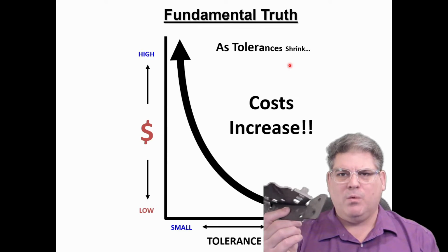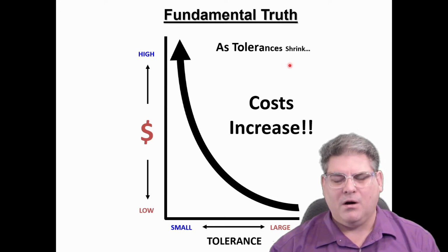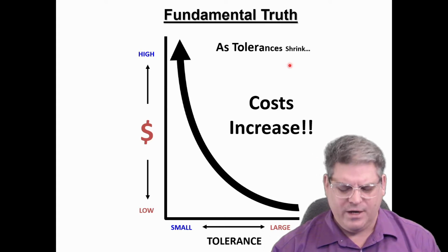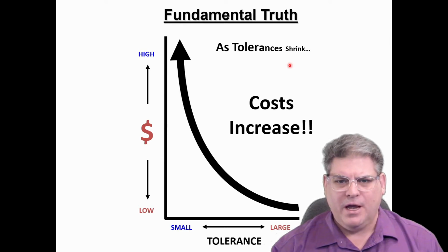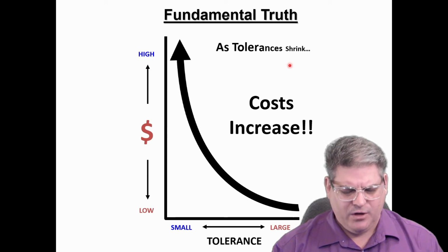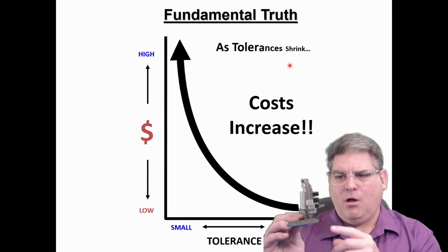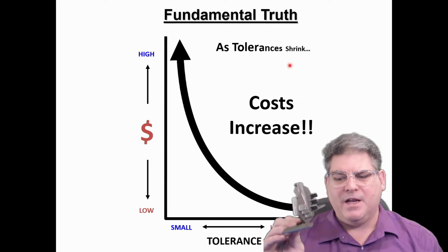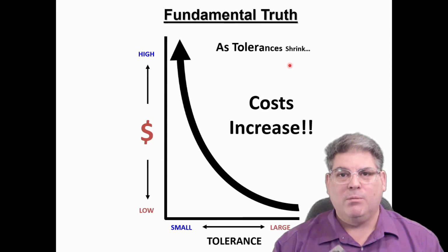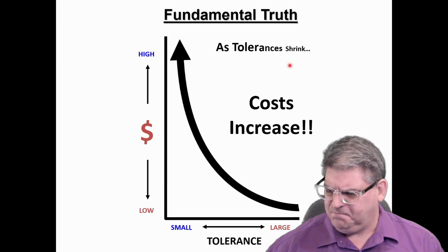And the thought, when we were designing the tooling for this, was, well, it's a lawnmower part. How critical could any of this be? As it turns out, very critical. The engineer came back and said, we want to hold the tolerance from this pinhole to this bottom edge within about 0.1 of a millimeter, which was surprising to us.